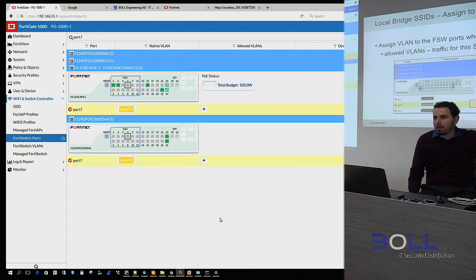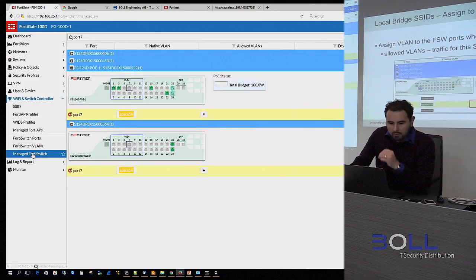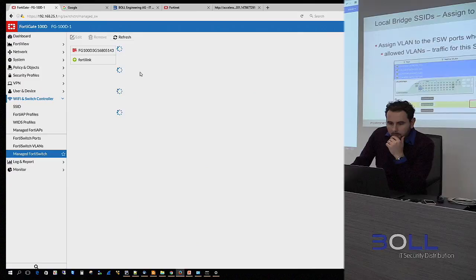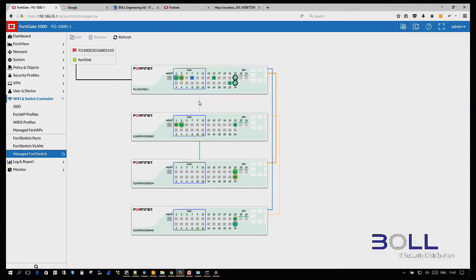There is an amber LED here that will tell you that PoE is working. So we can check now; we should refresh here and it should show us that we have PoE. If we check the switch itself with all the units, you can see the port is blue and it will tell you the power.